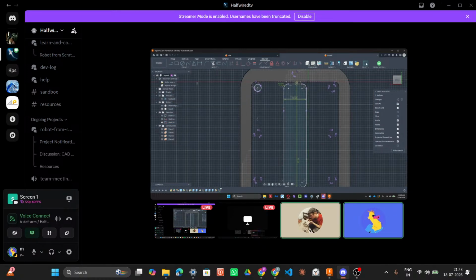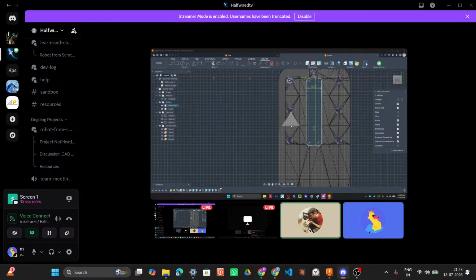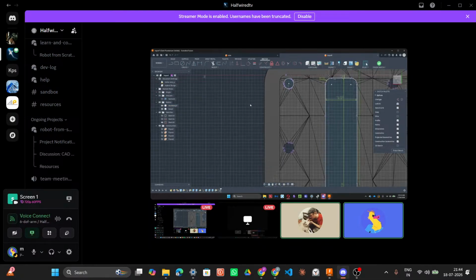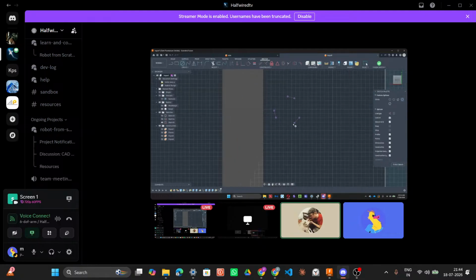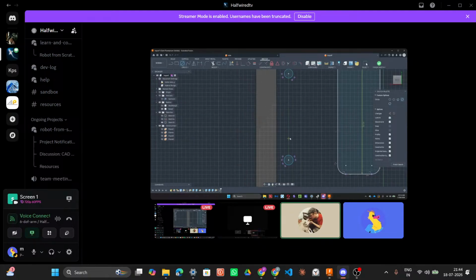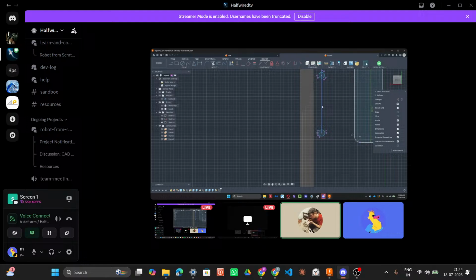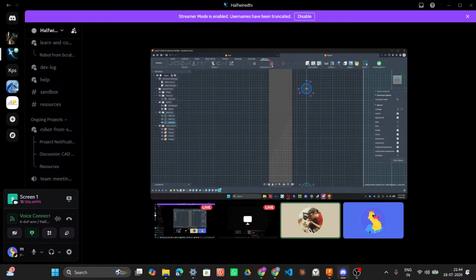And then like this, I'm gonna do the same thing because the mesh might not be perfectly in line, but it looks like those holes should probably all be in a straight line. So now I'm gonna do these circles not as tangents, but drop a line between them that is horizontal and make sure that they're all coincident on it.